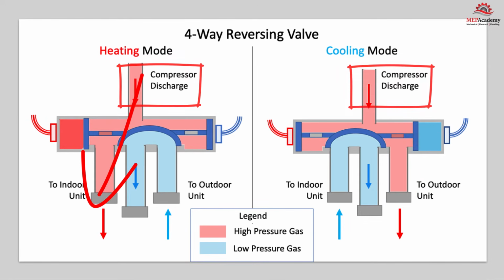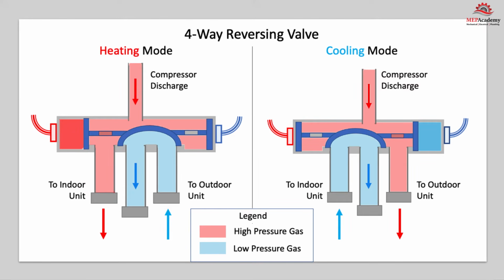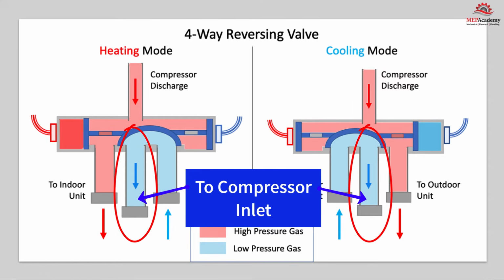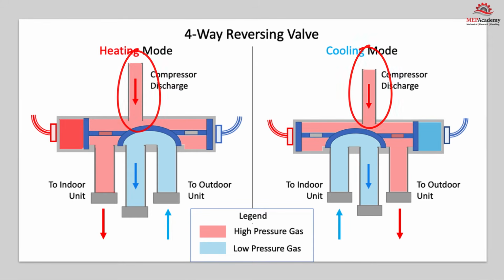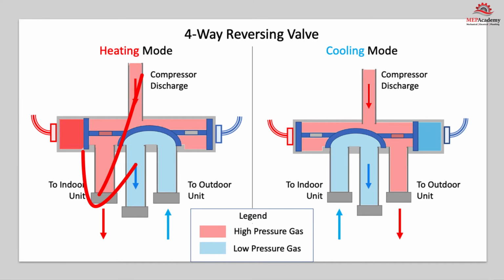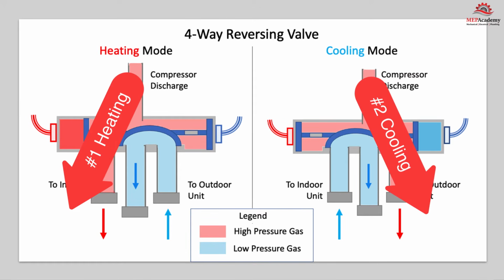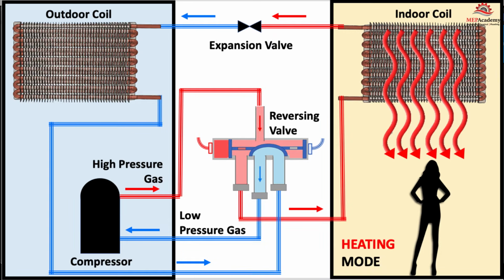In relationship to the compressor, cooling is always accomplished on the suction side of the compressor, and heating is furnished on the discharge side. What the reversing valve does is switch the compressor discharge to go to the indoor coil when heating is required. It's basically that simple, as the reversing valve acts as the traffic controller, sending refrigerant in one of two directions from the compressor. To understand this better, we'll walk through what happens in each season when heating or cooling is required.